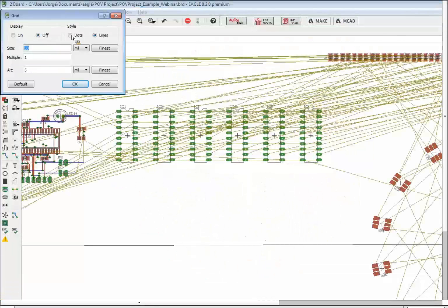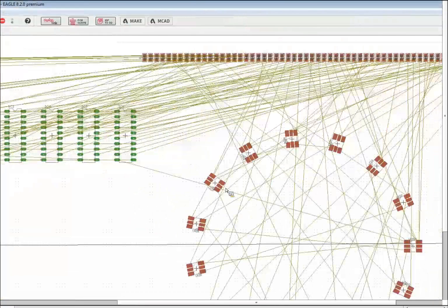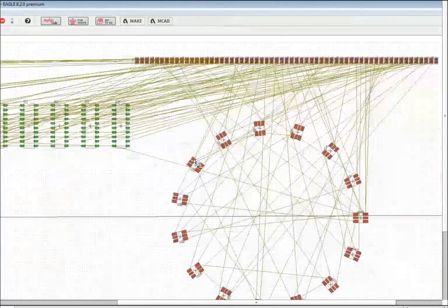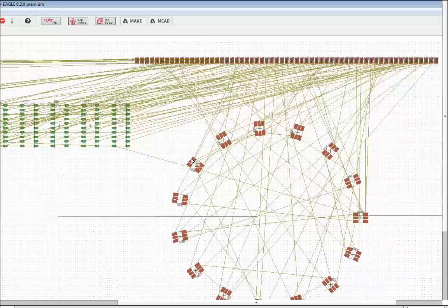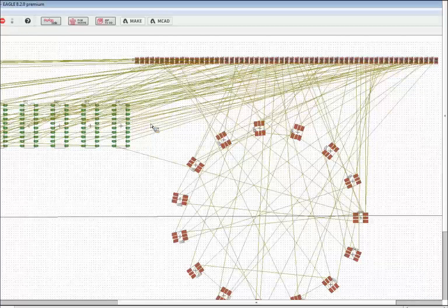But now that we have this alignment tool that gives you the grid option to align them up to a particular grid, which is actually kind of nice. There are also some very useful ULPs for aligning everything on a particular grid, or you could just use a regular move command to snap parts to a particular grid.